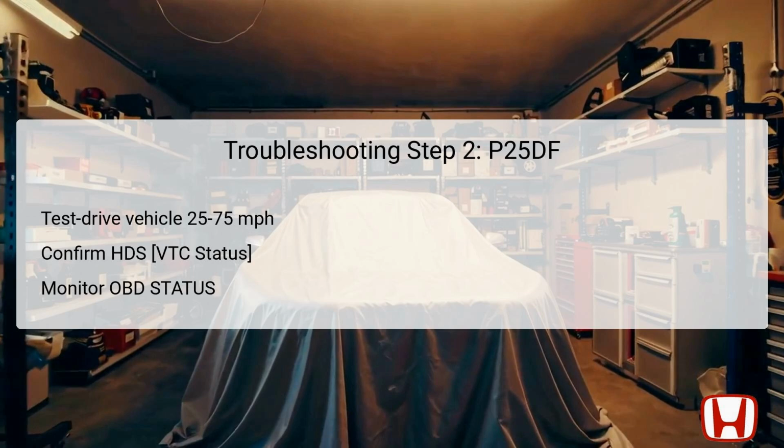After the test drive, confirm the VTC status on the HDS. It should display as on, indicating the system is active. Simultaneously, monitor the onboard diagnostics (OBD) status to check if DTC P25DF reappears. This step helps to ascertain if the issue reoccurs under real-world operating conditions, providing a clearer diagnosis.